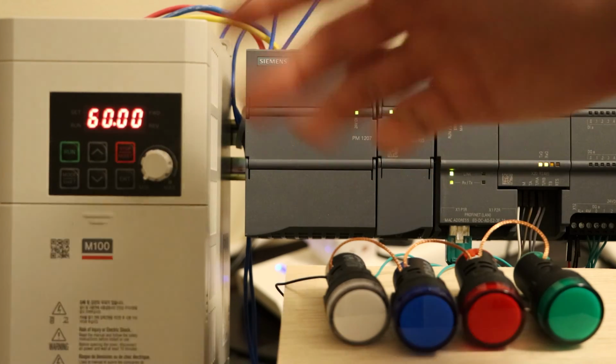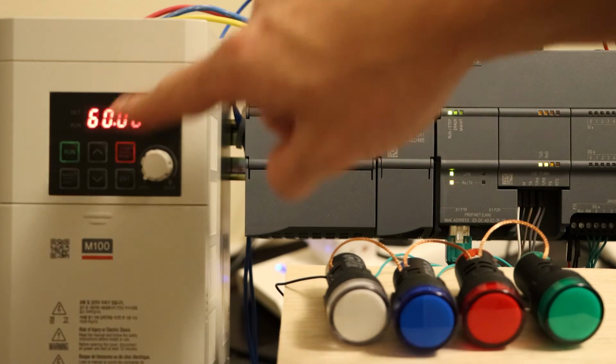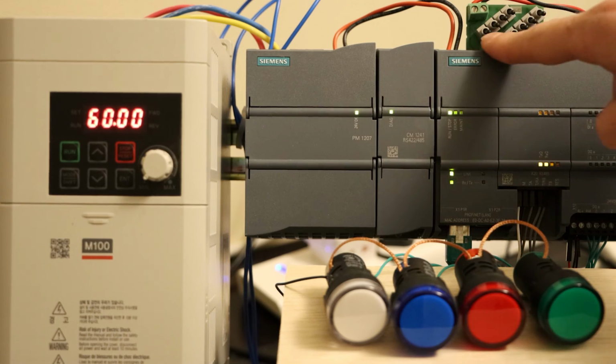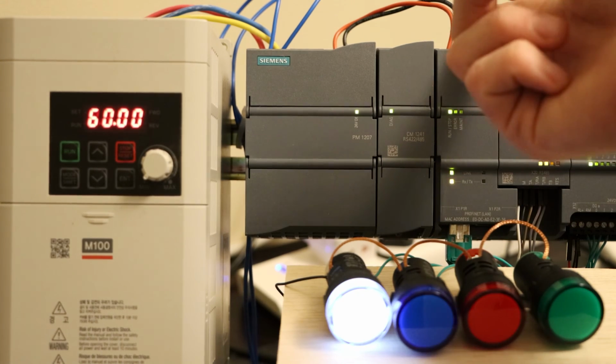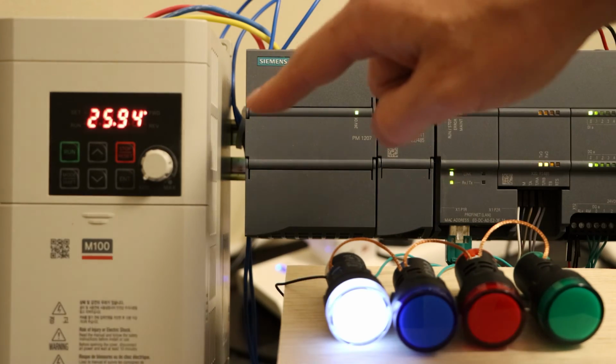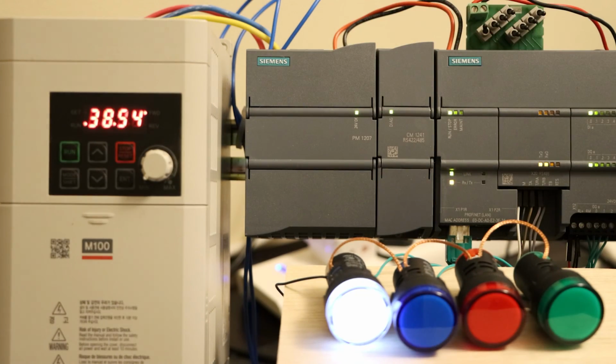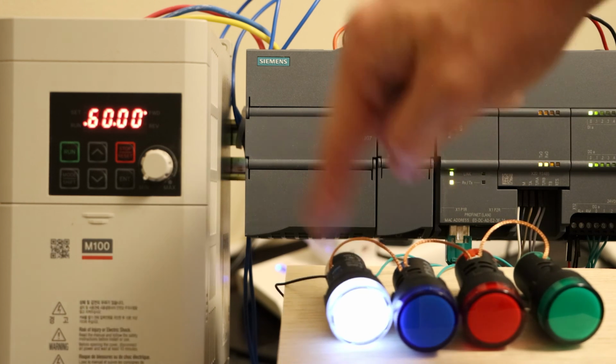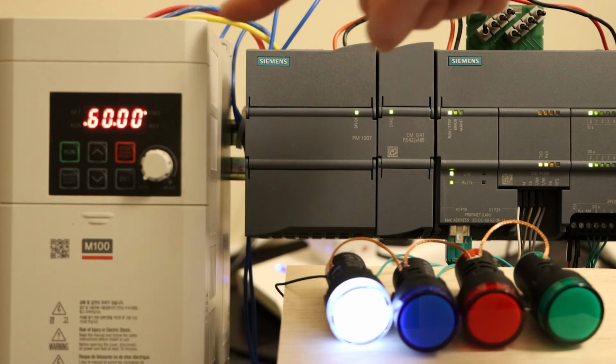So now we're at 60 hertz, but we're not running. You know, lights are on and we've got none of these running LEDs. If I pop up switch 1, you can see it just doesn't jump to 60 hertz. This will increase with the acceleration time that's been previously set inside of this VFD. So you're not going to burn out any massively inductive loads. So that's fantastic. So we can see our run light is on and we are running forward at 60 hertz.